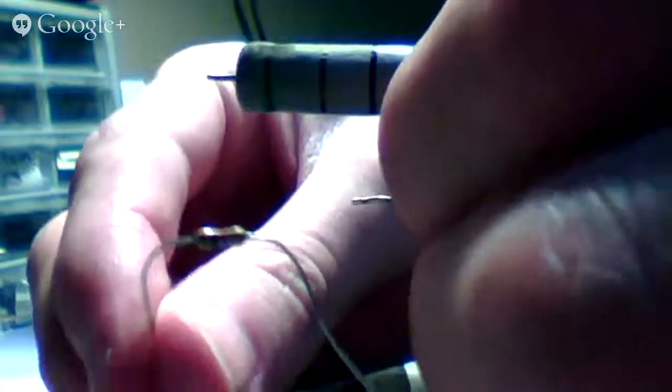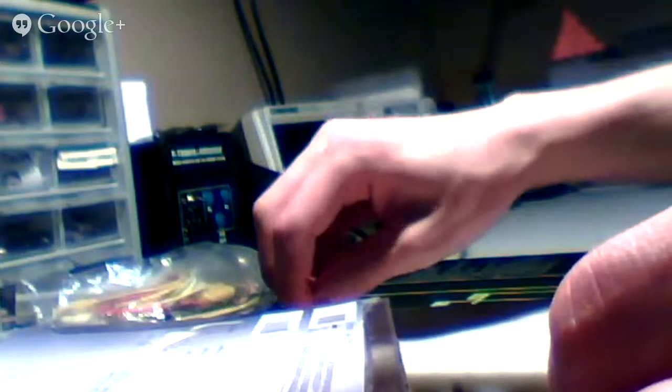This is a much bigger resistor. And it's not bigger because the resistance is a bigger value. It's bigger because this handles more power. This has more thermal capacity. It'll dissipate the heat much more easily than this little guy. This little guy would go up in flames if the resistance was low and the voltage was high. Get a lot of current going through there. We'll load it up.